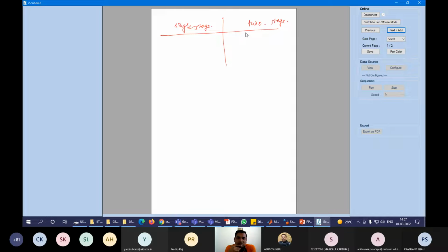So for what purpose have we taken the boost converter here? Obviously for MPPT purpose. So we cannot boost more than 20%. Up to 20% it is okay. But suppose your DC link requirement is 700 and you say I will put the number of modules in series so that I get a PV array voltage of 300 and boost from 300 to 700, that is not possible.